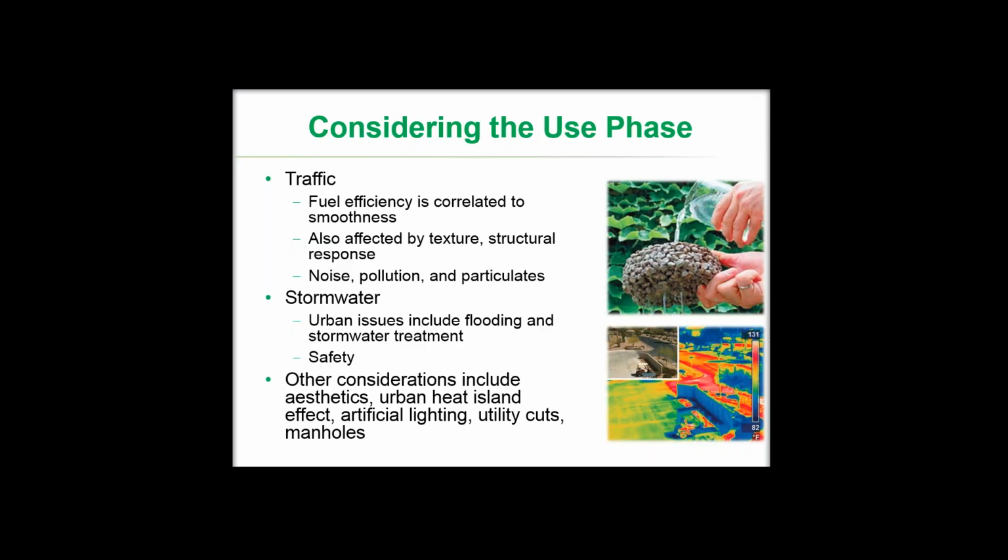Other things to consider for each project context include aesthetics, potentially urban heat island, lighting, utility cuts. If we design a long-life pavement and build it and it's cut up for utility cuts within a few years, we have not achieved our objective.